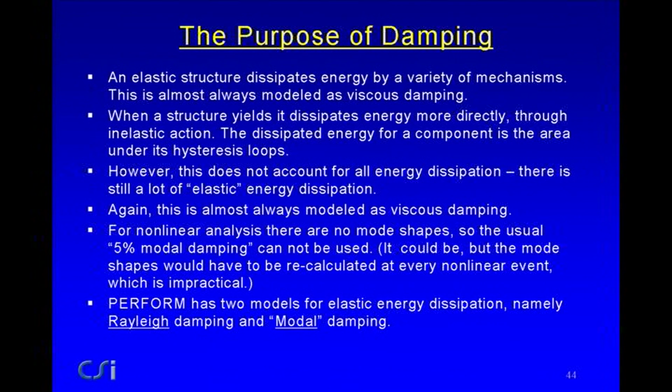So for nonlinear analysis, you have no mode shapes, so you can't just say, well, 5% modal damping. You can't really use that. And I do have a qualification here: as the structure deforms and the stiffness changes and hinges form and things like that, effectively the mode shapes change. Instantaneously you could say there are some mode shapes, and theoretically at every change in stiffness you could recalculate the mode shapes and then use modal damping. But that's a hideous amount of computation if you had to recalculate the mode shapes at every event. It's absolutely prohibitive, so you simply can't do that.